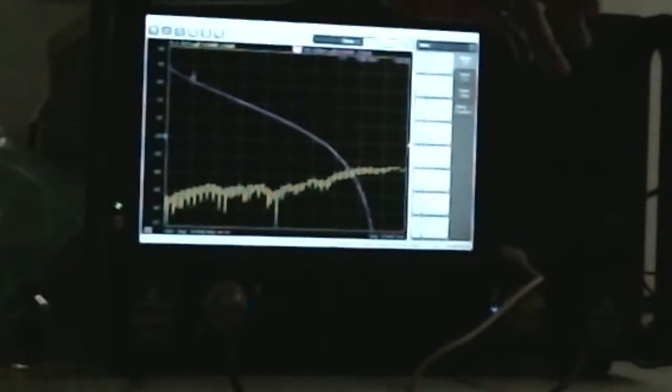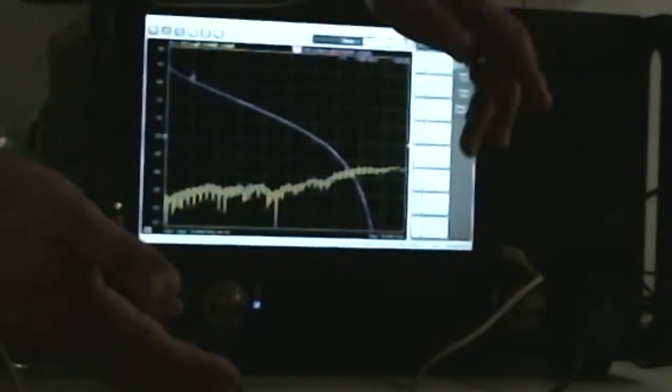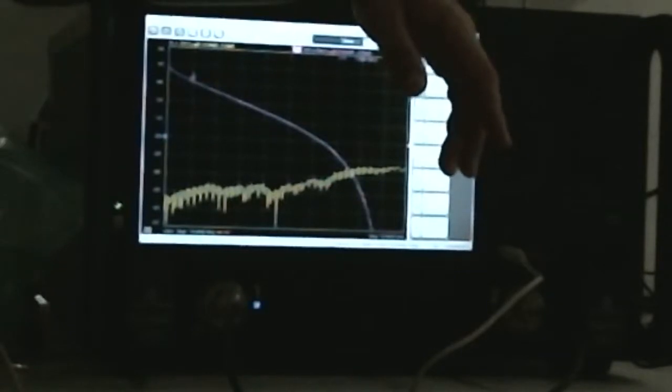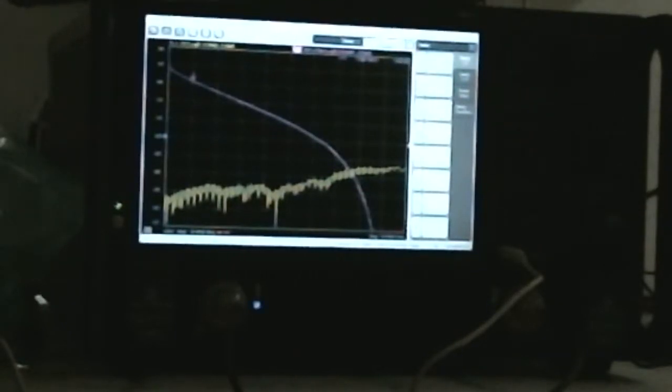So, hey, this doesn't meet what I designed in ADS. Why is that not working? Well, because your cables are not good, and you bent them a certain way. So if you want to eliminate that level of uncertainty... Again, if it's in a teaching lab and you say, okay, the filter has a response, the bandpass is roughly here, somebody's going to get the concept. If you're doing your doctoral thesis on this, definitely not the right way to go. So that's, like I said, what's the level of accuracy you need.